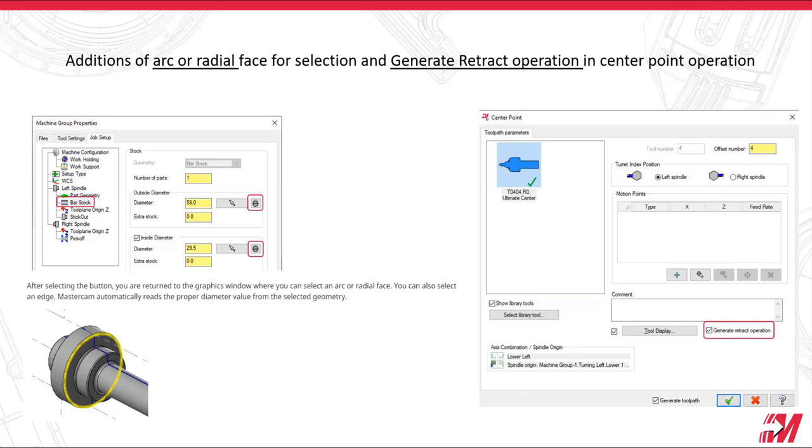And on the bottom right of the screen, there's a little generate tool path switch. That is added in all the tool paths in Mastercam with 2022. And what that'll do, if that's checked, as soon as you green check out of there, you no longer have to regenerate. It'll automatically regenerate for you if that is switched. So that is a nice button that they added in 2022.